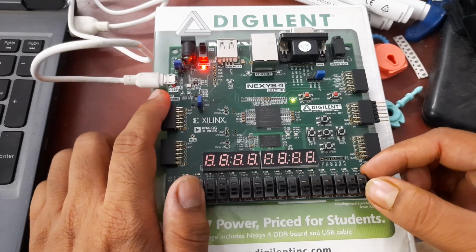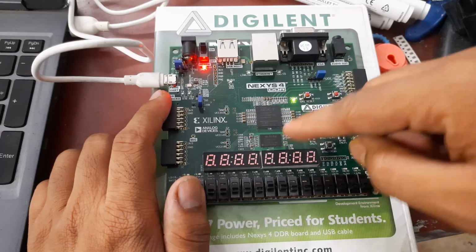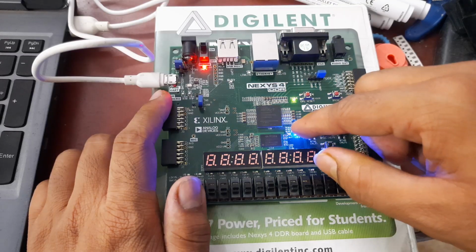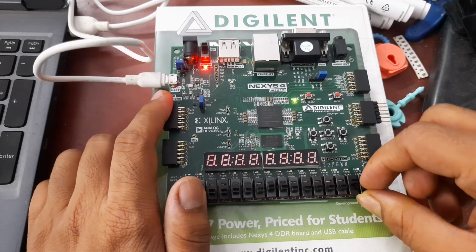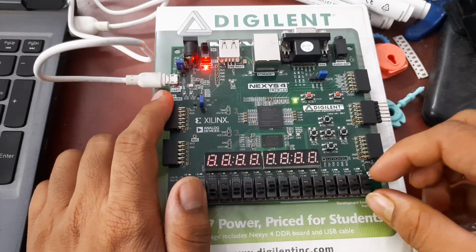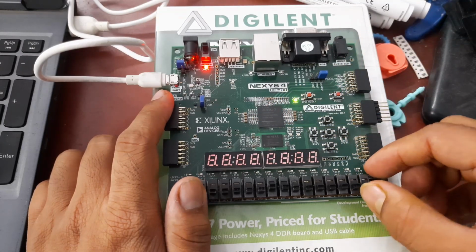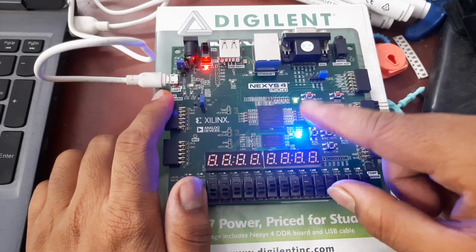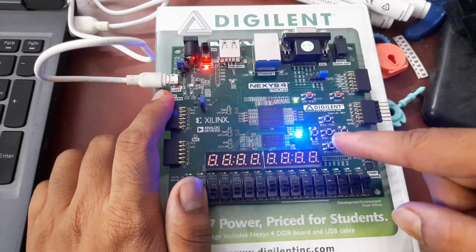So the functioning for 1 0, 0 1 and 0 0 is the same. 0 0, it retains the last state, so if I put it to 1 and if I keep it 0 0, it retains the last state, okay? When I put K is equal to 1, it basically goes to reset, right? And when I put it back, K is equal to 0, it retains its last condition. But what is going to happen when I put these two both as 1? It is going to toggle from the last state to the next state.